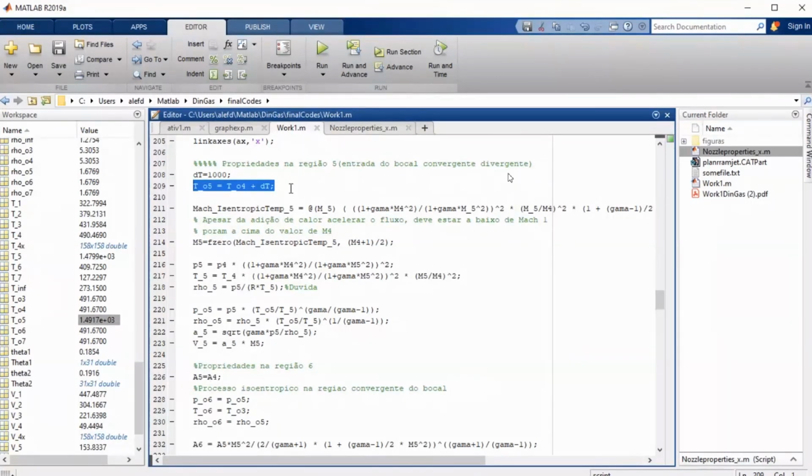I understand completely, because for each input Mach number, there is a limiting value of heat addition that this flow can sustain, to have the flow properties. Some flows cannot be heated beyond certain values, right? If the flow is too fast moving inside the cylindrical pipe, it physically cannot be heated more and continue moving. It will start to choke, as I already told you at the beginning of the class about the thermal choking. Yes, there is a way.